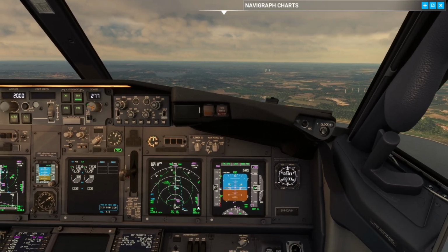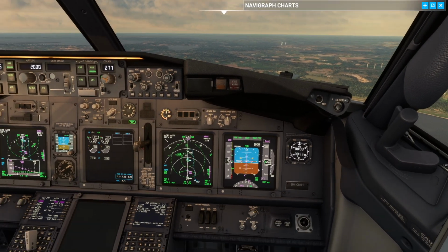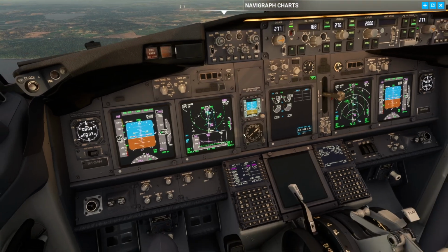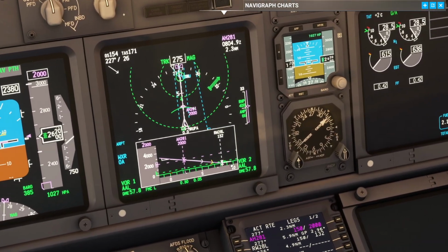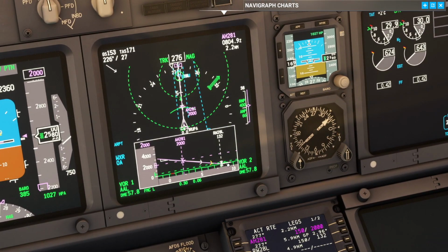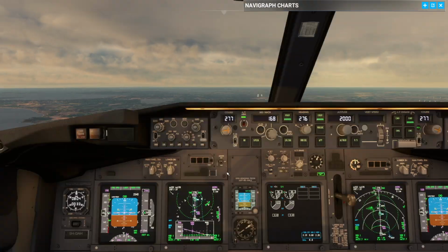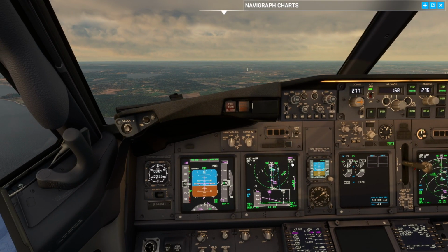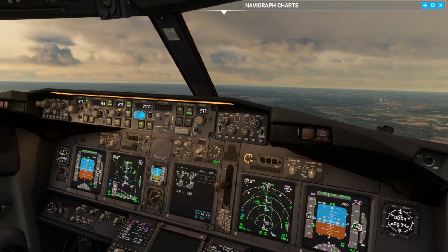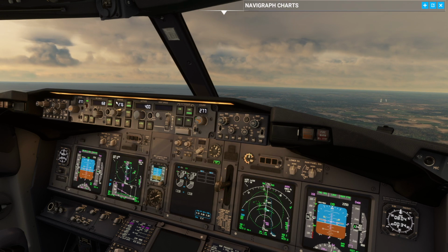$2,500. How far are we out? We are 9 miles, 8 miles, so that's perfect. So terrain is noted, and we can see here that the runway point is exactly on top of the terrain. So now we've mitigated QNH blunder error, okay? Approaching descent, alright. Revised MDA, 400 feet set. VNAV is path, speed intervene.